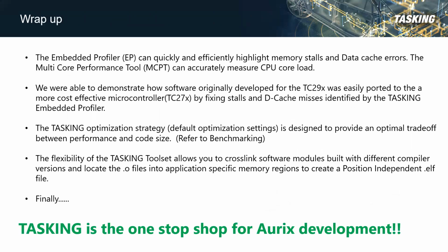Okay, and if I want to wrap up this particular webinar, you can see that I made use of a multi-core performance tool where I was able to accurately measure the CPU core load for CPU 0 as well as for CPU core 1. And by means of the embedded profiler, I was able to identify the stall as well as the data cache errors. We were also able to demonstrate how the code can be easily ported from a higher microcontroller to a lower microcontroller with a low flash size and a lower RAM.